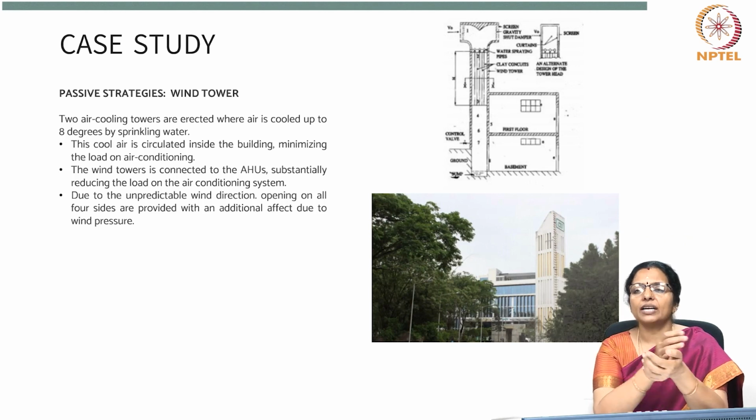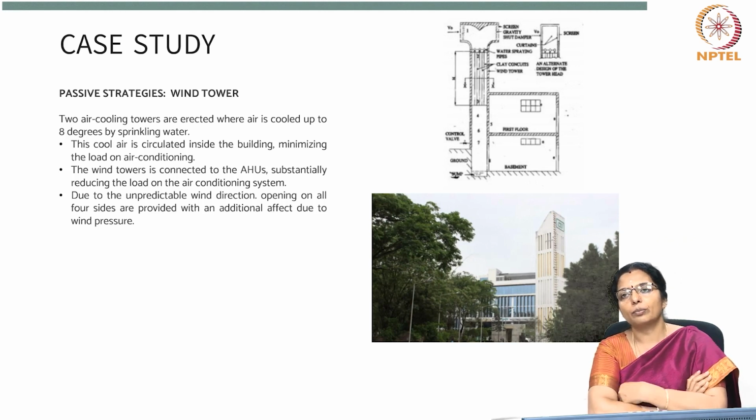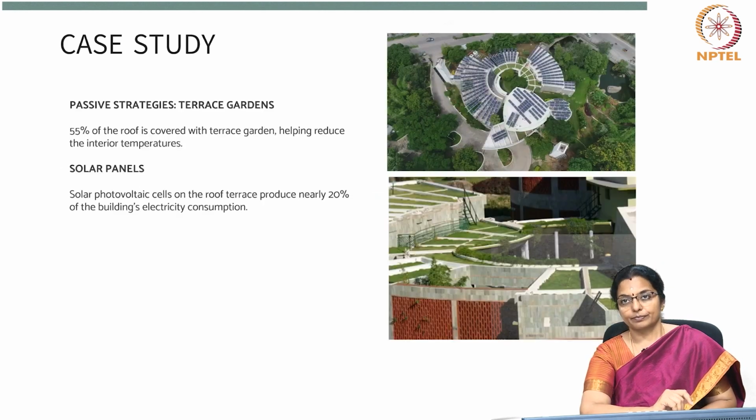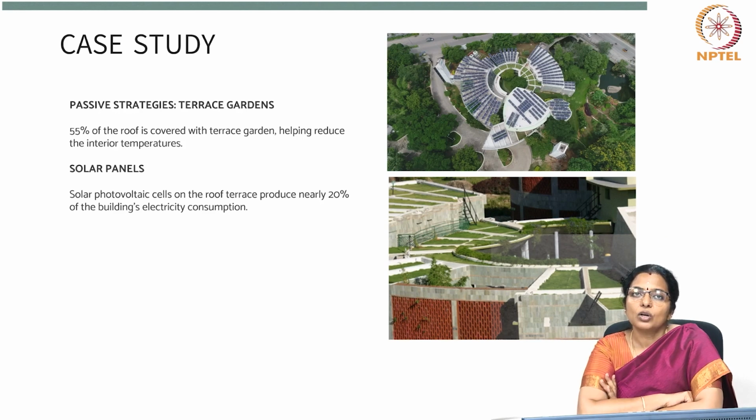Due to the unpredictable wind direction, openings on all four sides are provided, with an additional effect due to wind pressure. Now, because of the use of some of the other advanced passive techniques such as terrace garden and solar panels, a lot of energy savings has happened.